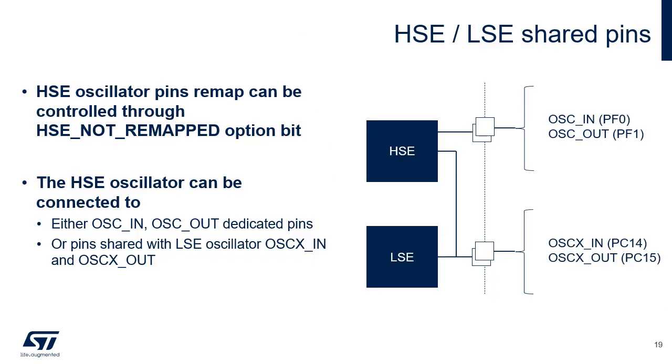STM32C0 introduces pin sharing between high-speed and low-speed oscillators, providing flexibility, particularly in low pin count devices. For example, PC14-OSC_IN and PC15-OSC_OUT are shared by both LSE and HSE, meaning these clock sources cannot be used simultaneously.